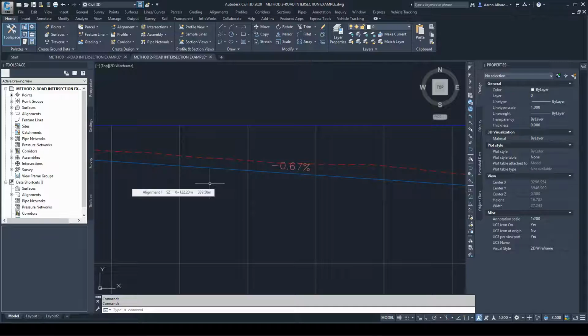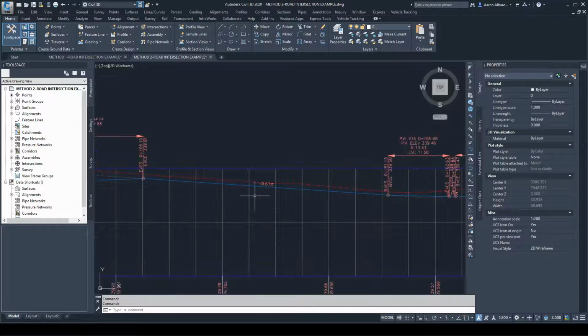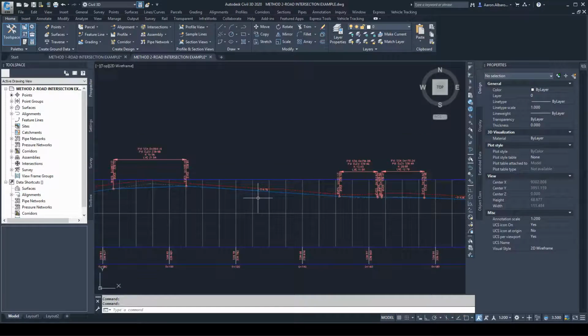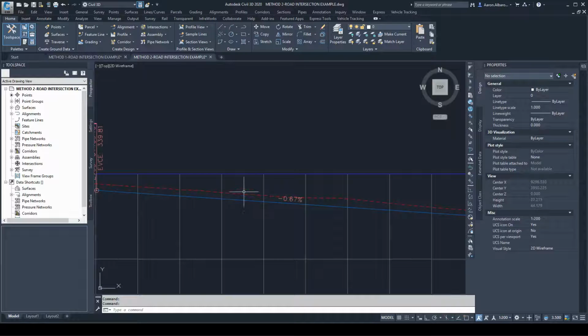Also, we're not too cautious about the speed of vehicles traveling on these roads. We're expecting vehicles to slow down and to be more aware of their surroundings in urban developments. That's what creates the additional road furniture or structures that we see on the road, such as small roundabouts or barriers, to give the driver the perception to slow down. If you have any issues with dice, you can check the previous video, where we talked about that too. So, long story short, for urban design, let's keep the profile as close as possible to the existing ground.